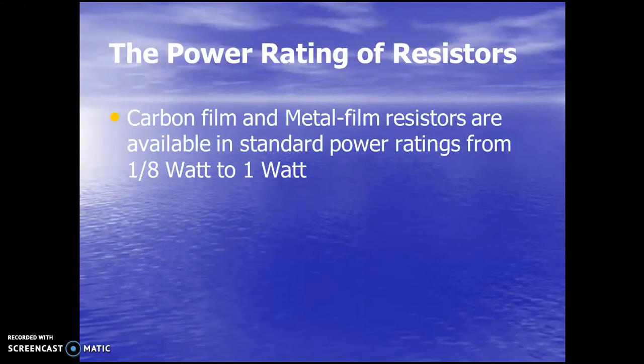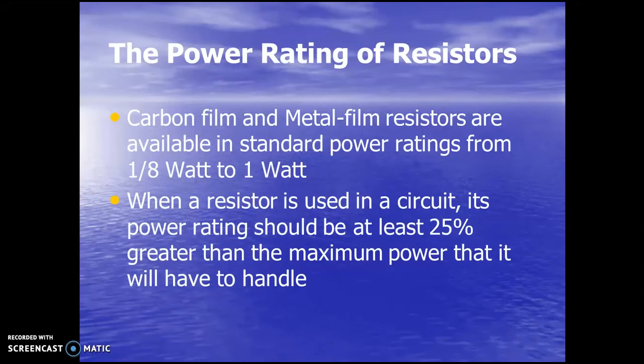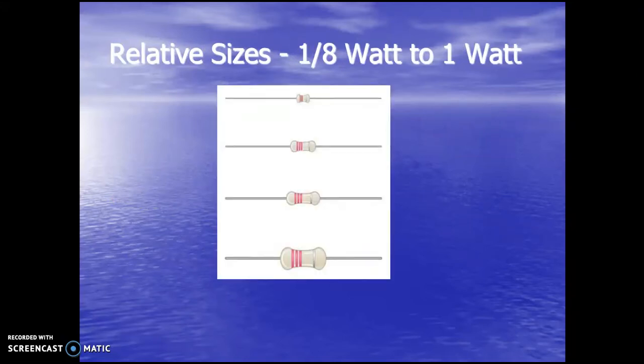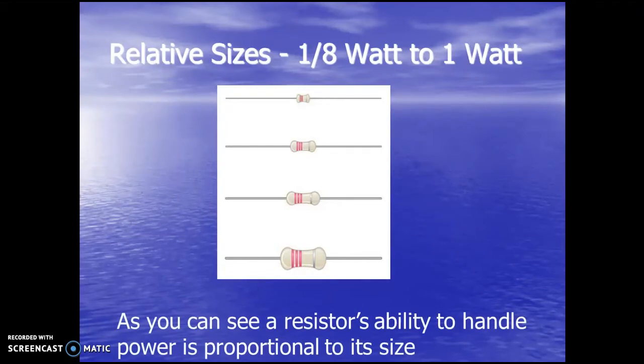Okay, and the resistors we'll most typically use, their power ratings are typically from 1/8 of a watt to a watt. I think all the ones in our classroom are either 1/4 or 1/2 watt resistors. You want to keep well below that. So make sure your resistor is over specifications so that you don't have any issues in the operation of your device. And relative sizes for what it's worth, of course, the resistors get bigger as their wattage goes up.